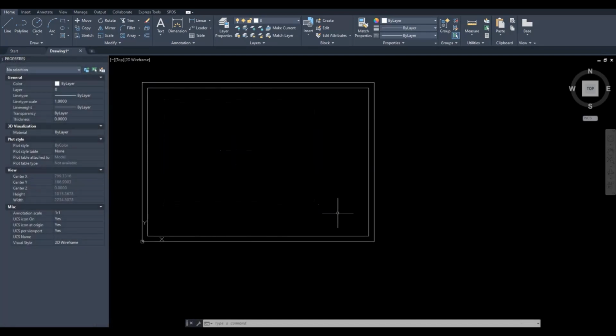Next up, we'll be adding the information bar, or where we'll be placing key information relating to the drawing. Usually, the information bar is added on the right hand side or the bottom of the title block. In our case, we'll be placing it on the right hand side. For the main titles, we'll be using a text height of 3 millimeters, and for the information itself, we'll just reduce it a bit, perhaps 2.5 millimeters.